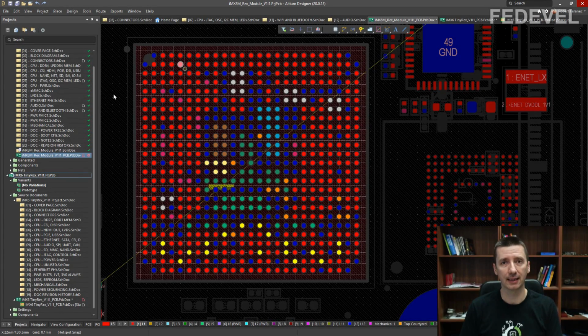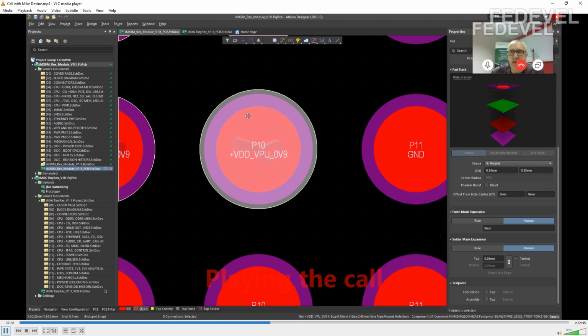So I asked Mike, and this is his answer. If you need to send them only one or two drill files. In the engineering cycle, when they're doing the full DRC check, they will highlight those holes which are in CAD and split that onto its own drill program. Okay, so one drill file is just fine for you? Yes.